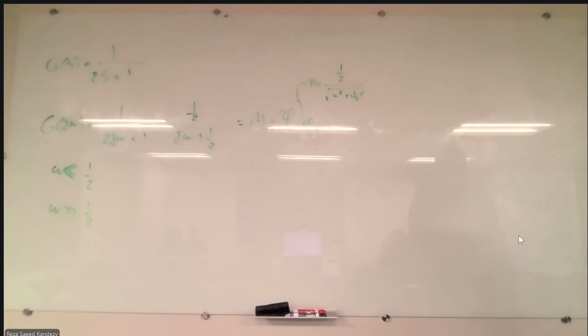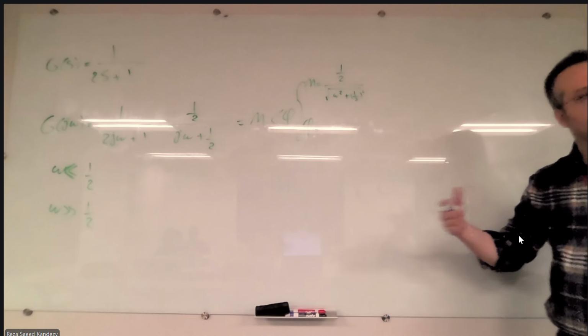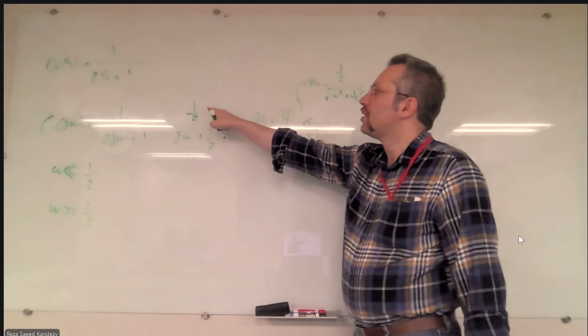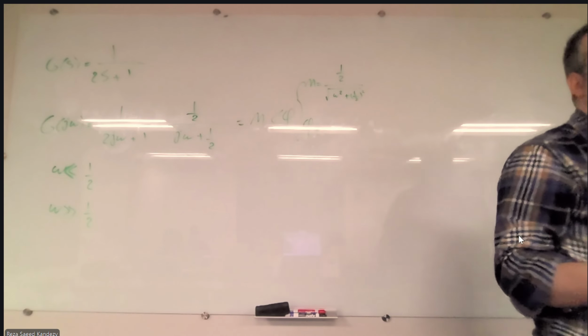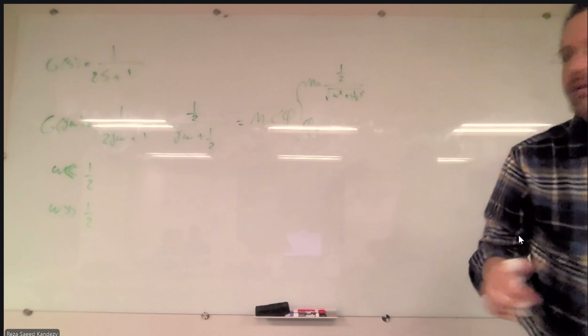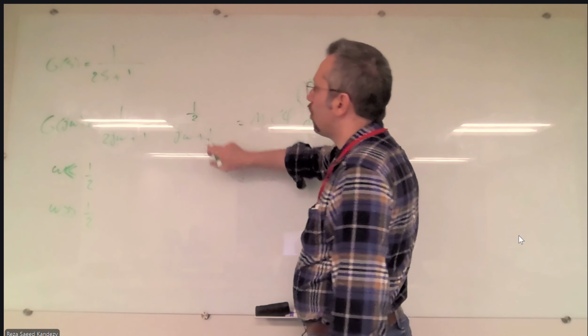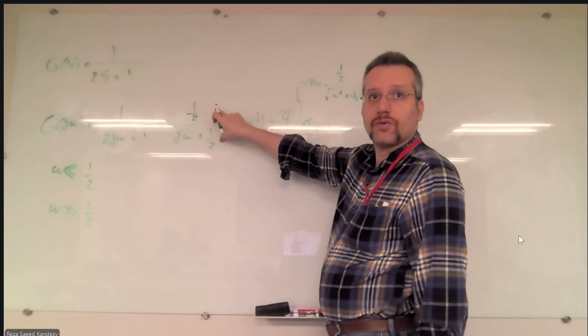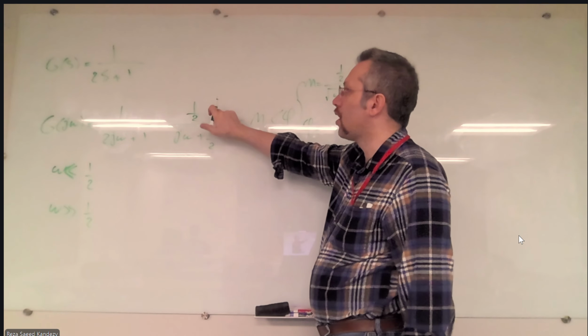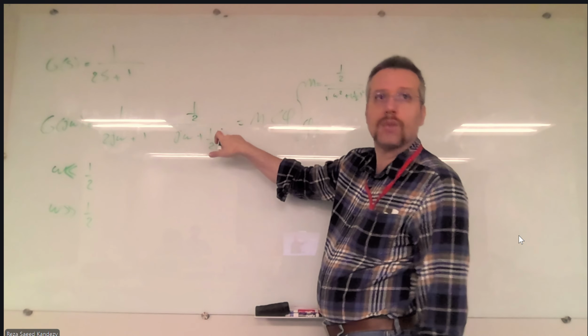And the phase is simply going to be based on that tangent relation between the real part and imaginary part. The numerator that we have is a constant number, so its phase is going to be 0. We know that when we have a division of complex numbers, the phase of the overall situation is the phase of the numerator minus the phase of the denominator.